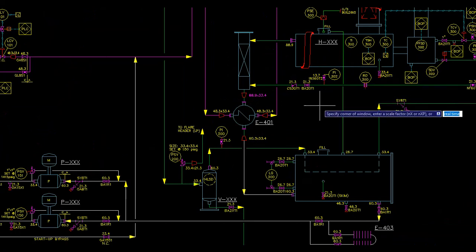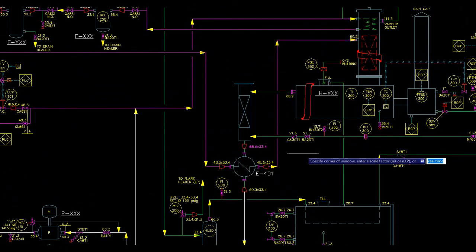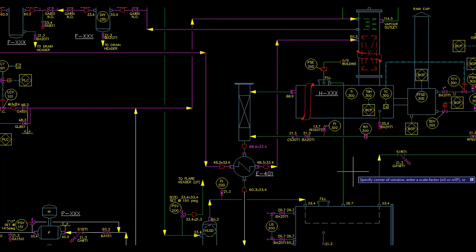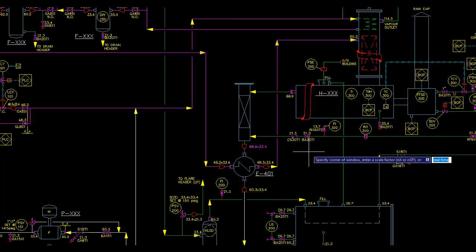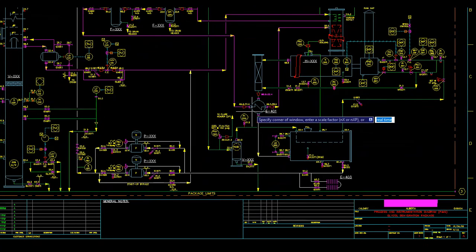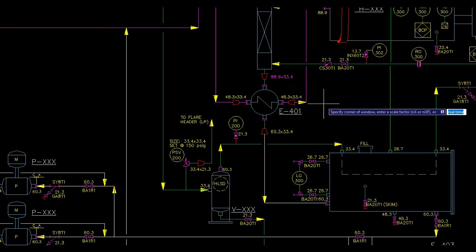This is further explained in the GPSA if you are interested, where you can actually size the amount of gas that should go in as stripping gas in order to enhance the dryness of the lean glycol, because gas has an affinity for any water that this lean glycol is carrying out.